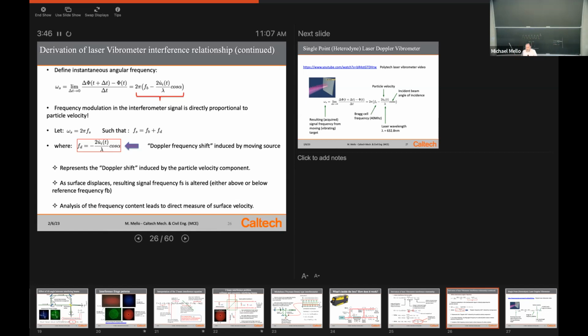All the hardware and software you're buying is doing that for you. It is doing fast Fourier transforms, and it is figuring out where is your signal instantaneously, okay? And as the frequency of that signal varies, the net frequency of this signal translates immediately into the velocity of the surface, okay? And it can detect now whether the surface is moving toward you or away from you.